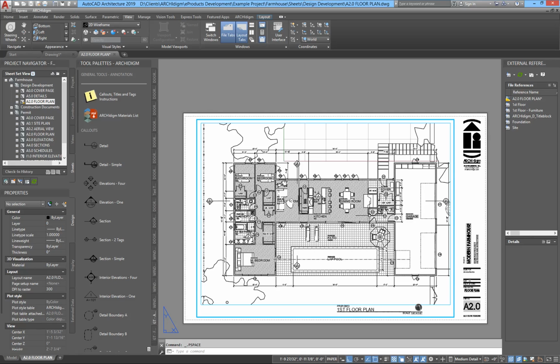So I don't like taking a full sheet file. I usually don't want to give anybody my title blocks anyway. I do have my dimensions. It's tough if I want to pass those on, but I would actually prefer to pull up the floor plan and then maybe cut and paste the dimensions into it so I can give a cleaner version. And you can see why, because of all of those blocks and all of that stuff I have to explode through to do cleanup work. I found that this is a better approach.